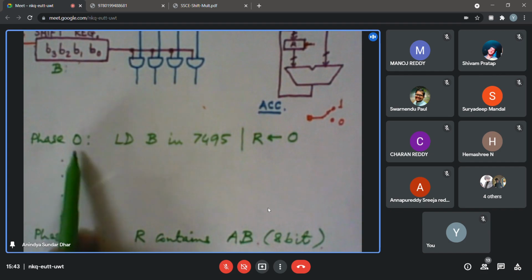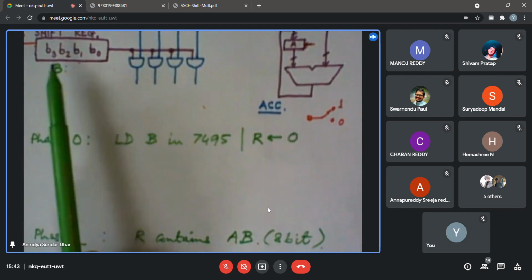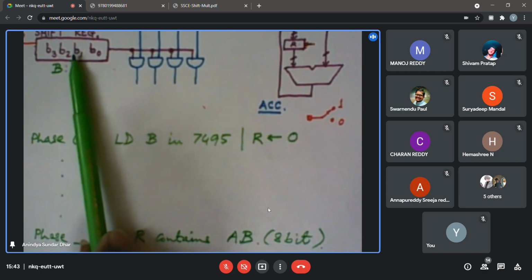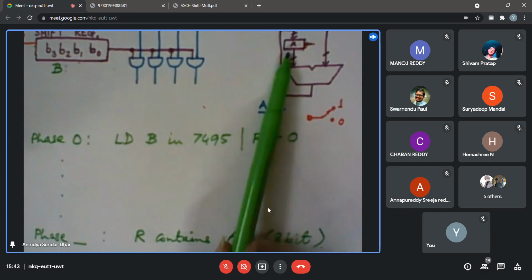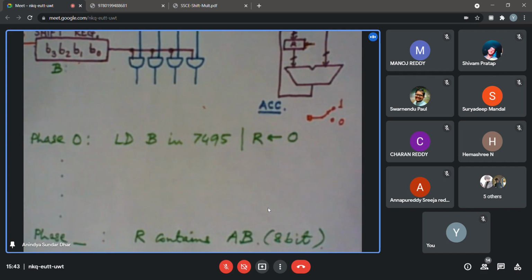So how many clock cycles do you think in between I need for this accumulation? One clock cycle I will certainly require for loading at this point. And this 74273, its clear, I think you have used earlier. Is it asynchronous clear or is it synchronous clear?